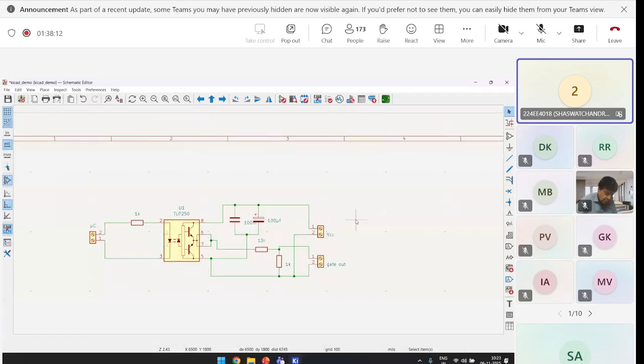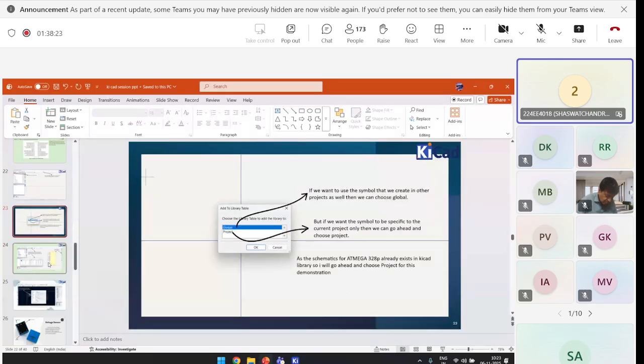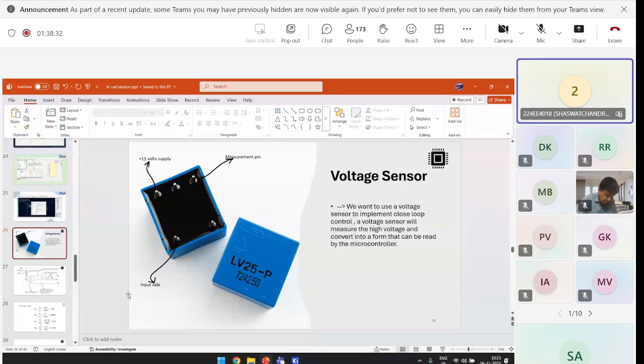So after this, up until now, we have seen the buck converter and designed the gate driver circuit. Here we are giving 0.5 duty cycle, or any other duty cycle for that matter, and we are driving the buck converter, right? We gave 0.5, the voltage is cut in half. We gave, let's say, 0.25, the voltage is cut to a quarter.